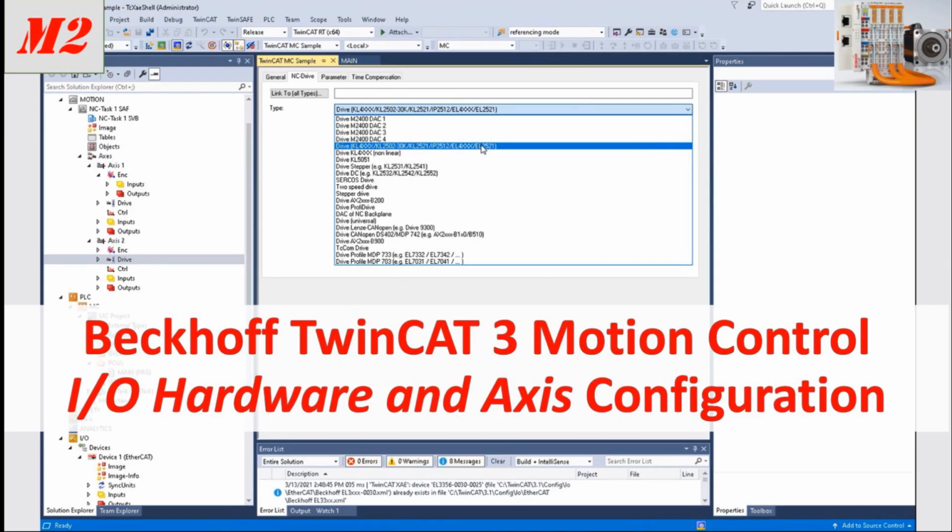Hello everyone, in this video we will mainly discuss how we can create a TwinCAT 3 project for motion control, and how we can set up the hardware configuration and motion axis settings. I will go through the motion axis settings in this video.